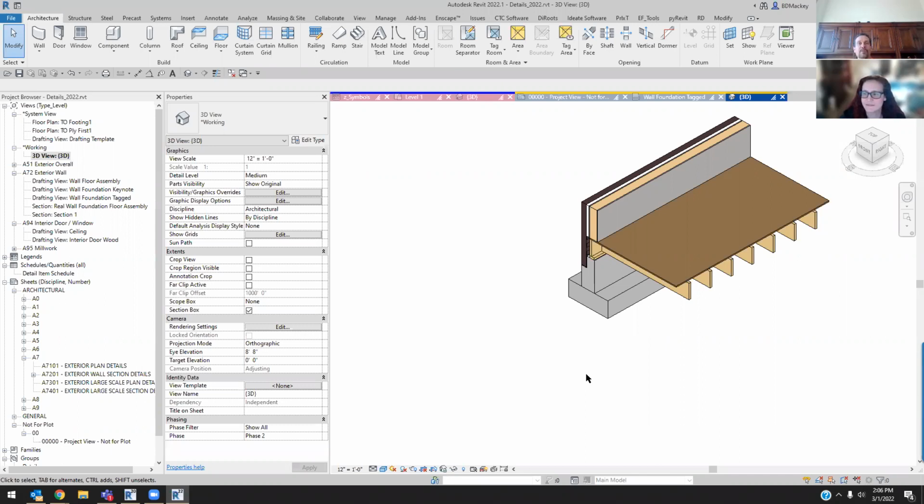And Melissa now learned something new as well. I know, now you're going to be exporting all sorts. Oh, I love it for that. I had a client where I just needed to do a simple little walkthrough on this crazy handrail in this art pavilion. So I just did a section box around it, said export. I got the walls and floors and ceilings and said, here's your handrail. And it worked great for the 3D DWF and everything else I gave them. So I use it not often, but probably once a month.